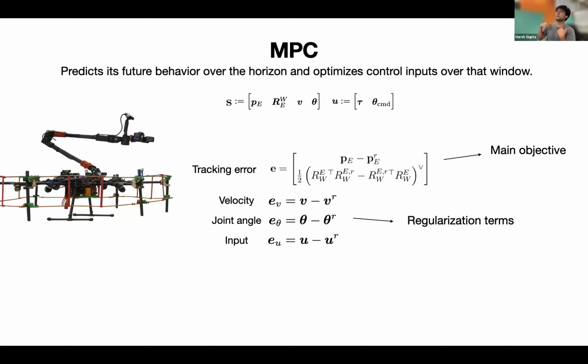It's very detrimental to have the drone's arm really far extended out, because that makes the drone's base or center of mass messed up. It makes the drone's base tilt in front, which is unstable.